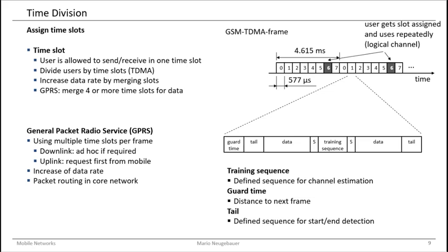Additionally to this radio subsystem principle for GPRS, we also have to add some switching in the core network, and that means that after the base station controller, the data is split from the voice call, and the data is transmitted then into a data network so that the internet connection can be set up and all the required data are transferred from and to the mobile station.